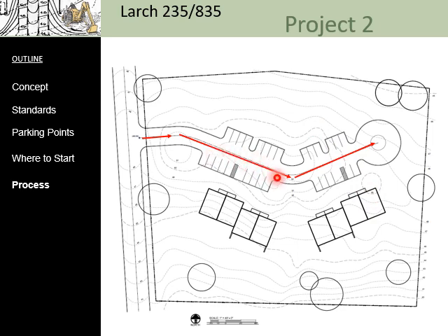So now you've got some understanding of the centerline elevation and then the elevation at the front of the buildings. Now you have to jump down to the back of the building, and that's a 9-foot drop off. So you start with this elevation, you figure out what's a reasonable elevation to get to the building, and then what is a reasonable elevation to get back down to the patio spaces behind where you drop 9 feet.